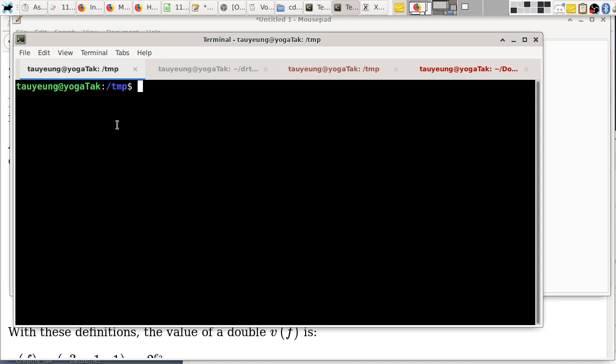Because with an 8-bit architecture, you can only add or subtract 8 bits at a time. The mantissa itself is technically 53 bits wide. So that means you have to use 53 divided by 8, and take the ceiling of that, which is 7. 7 times 8 is 56, right? So it will take 7 individual additions to add the mantissas of 2 numbers. So it will be really slow, but it can do it.